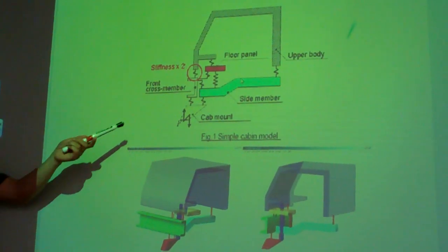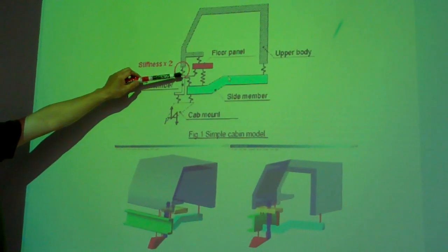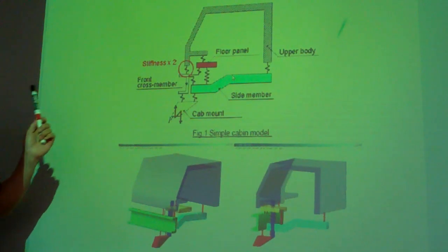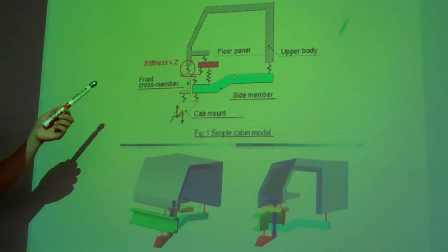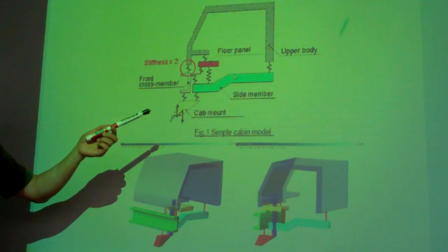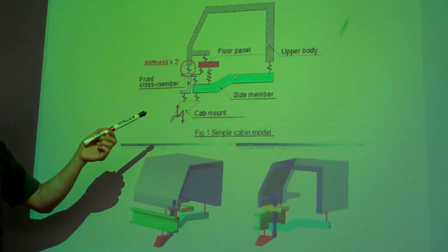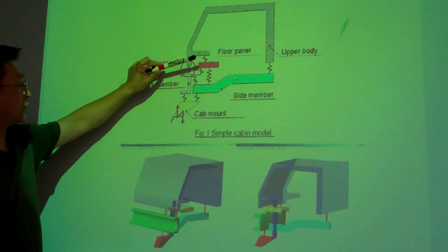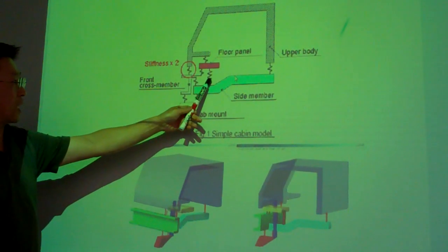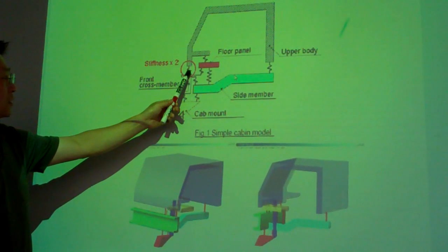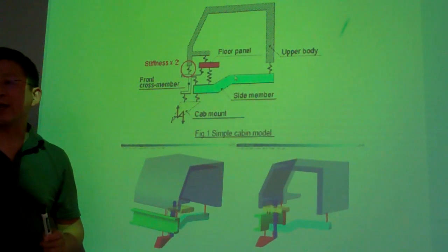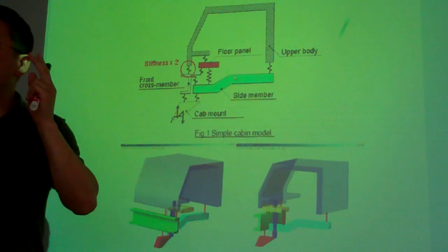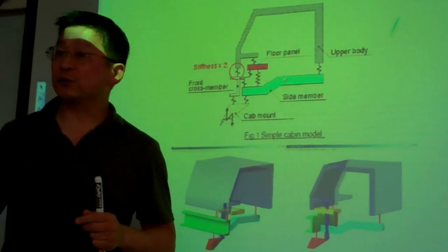And that is the machine, and for example, this is a car, say a truck. This model is a discrete model, used quite commonly in the automobile industry. Basically they use lumped mass, lumped spring, and lumped damper. Different car models have different know-how, and that is a business secret.